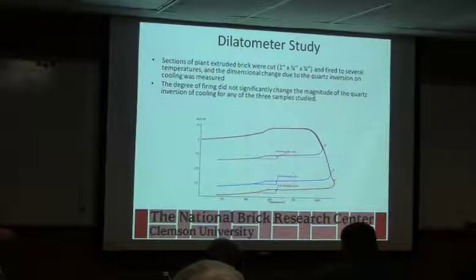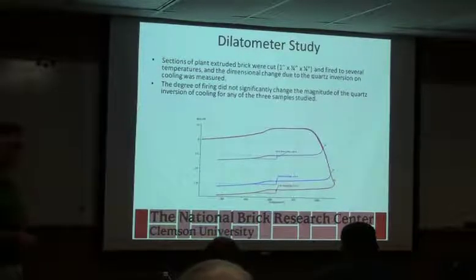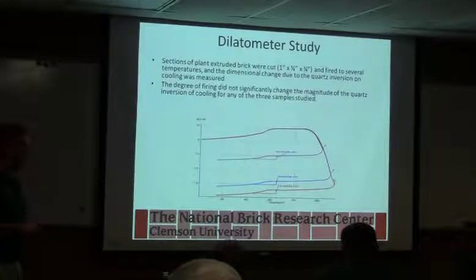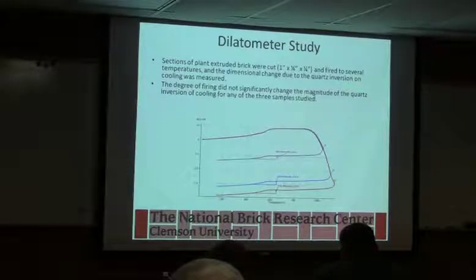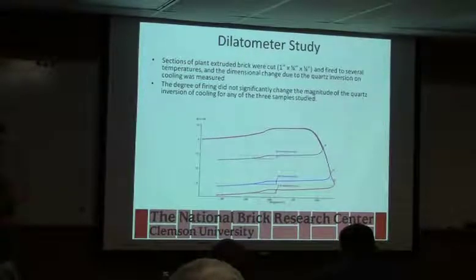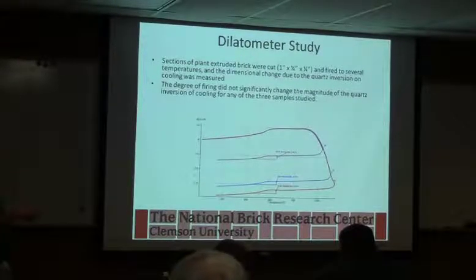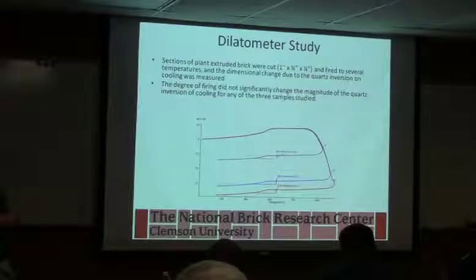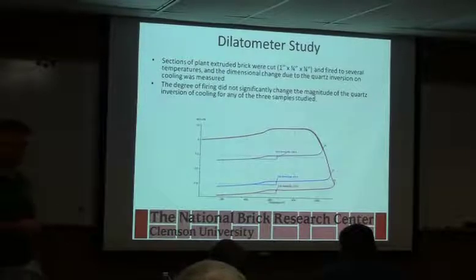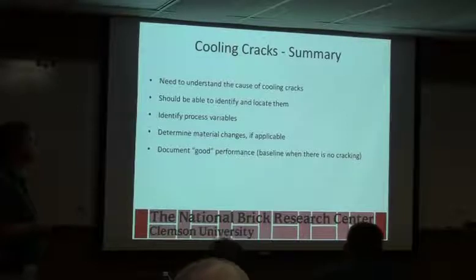It's always happening at the same temperature, always going through the same phase change. So adjusting the temperature you're firing to isn't going to affect how the quartz responds. It's more what you do going through this temperature and how you mitigate the stress, which usually is going to a slower rate through that temperature range.